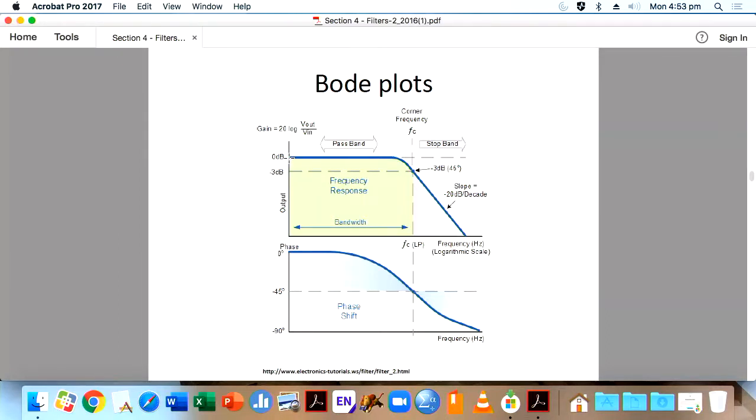Unity gain filter. Then when you look here, gain equal to 1 for 0 hertz, gain equal to 1 for 10 hertz, again 1 for 100 hertz, and then maybe this is equal to 1k, that is your cutoff. Up to 1k, your gain is constant. After that, 1k is our interest. We don't want anything beyond 1k, but because of this slope, still maybe up to 2k, signal will pass through because of this region.